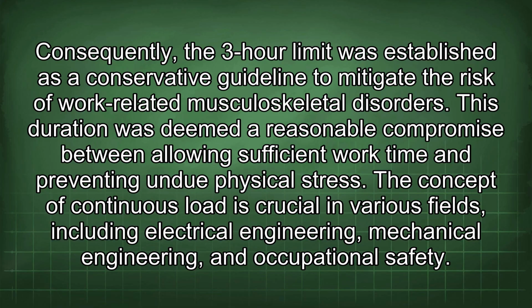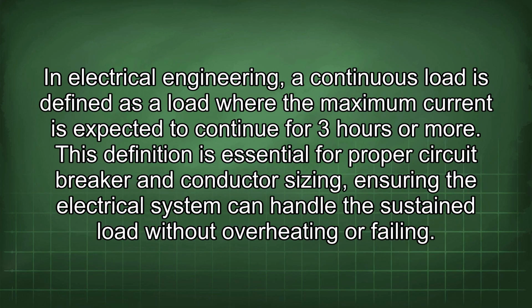The concept of continuous load is crucial in various fields, including electrical engineering, mechanical engineering, and occupational safety. In electrical engineering, a continuous load is defined as a load where the maximum current is expected to continue for 3 hours or more. This definition is essential for proper circuit breaker and conductor sizing, ensuring the electrical system can handle the sustained load without overheating or failing.